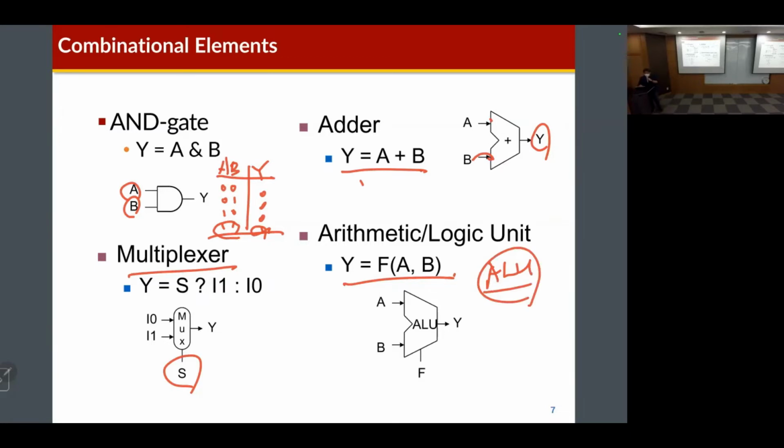So the ALU receives the two input data A and B, and the function of this ALU is determined by some selection control signal, the ALU selection control signal. And then based on this defined function, the ALU generates the defined result. Okay. So our processor will include the ALU because in chapter 2 we learned about the various arithmetic and logical instructions of RISC-V.